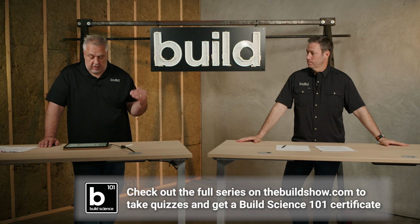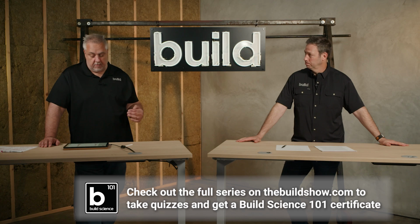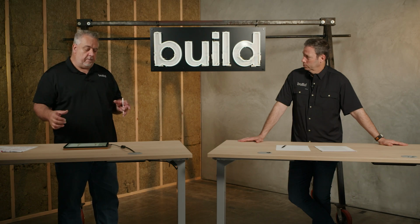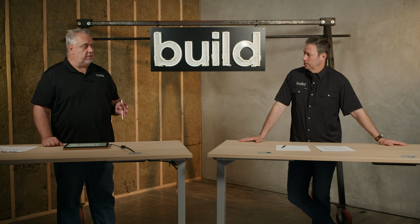Like we talked about in water management, I broke this one down into 3 very simple concepts. There's the concept of continuity. Write that up here. Basically, the concept of continuity is the key to airtightness management. Pay attention that we didn't call it air barrier, which a lot of people like to think about, because the air barrier is far more complex and a wider spectrum than just an air barrier. It's a whole management system when it comes to airtightness.